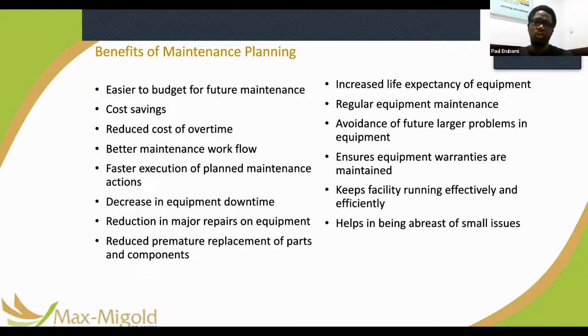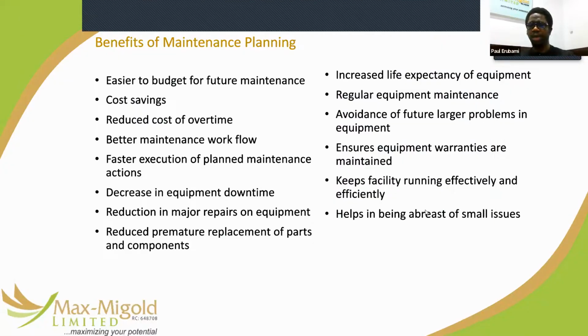And then, of course, if you maintain frequently and you have a good plan to practically maintain, you would avoid future problems, because usually what happens is that assets fail like a domino effect, right? So if a moving asset has a belt that wears out, the belt cuts, what are you going to get? You're going to get some parts of the engine overheating. You're going to get some burnt gaskets. So there'll be a ripple effect from just that belt cutting, right? So you don't want that compounding of problems because you did not pay attention to a belt.